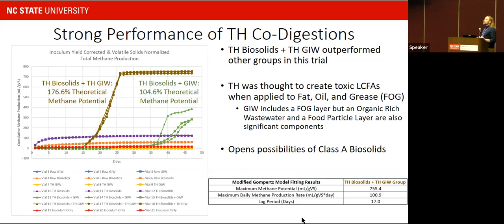That is, you can calculate the theoretical amount of methane that is possible to be generated, and we do this by only including the substrate energy content and then comparing it with what we expected to see. And in both of these trials, we're seeing more methane than was in the energy content of the substrate, which suggests that something about these co-digestions helps access the methane potential, allowing the community to get into the energy content of the substrate.